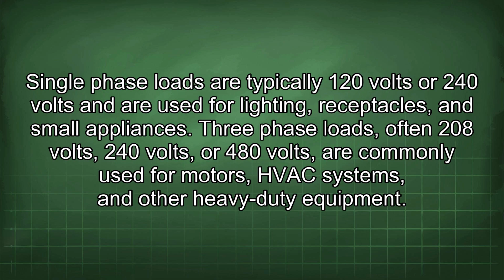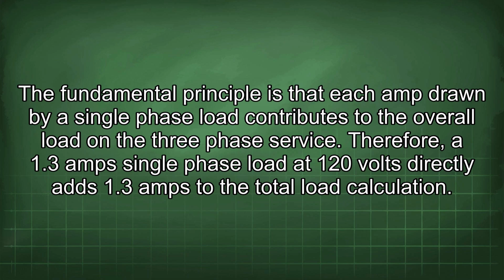Three-phase loads, often 208 volts, 240 volts, or 480 volts, are commonly used for motors, HVAC systems, and other heavy-duty equipment. The fundamental principle is that each amp drawn by a single-phase load contributes to the overall load in the three-phase service. Therefore, a 1.3 amp single-phase load at 120 volts directly adds 1.3 amps to the total load calculation.